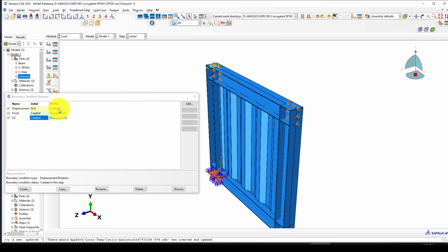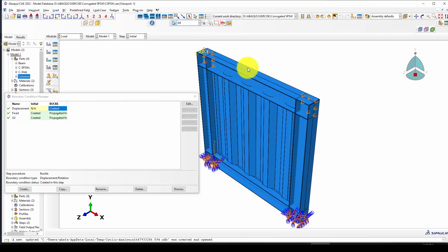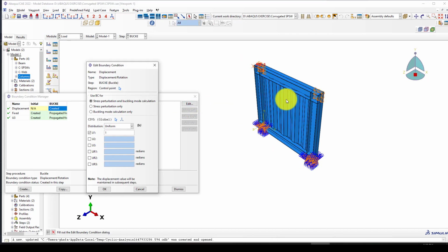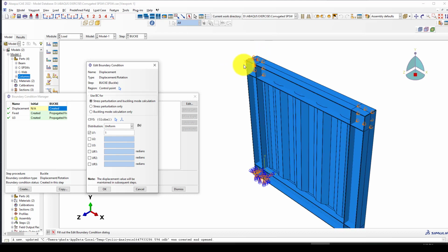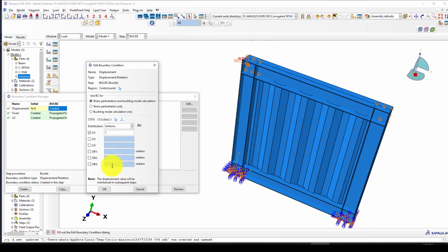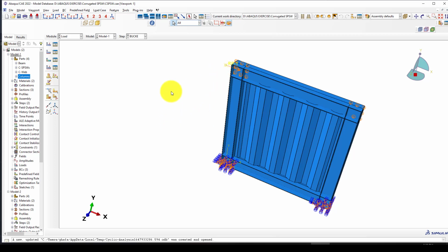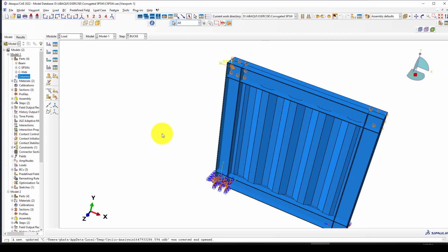Now in the buckling, instead of applying a buckling load, I want to apply a displacement. So the displacement is given as 1 unit at that control point, and we want to know, for 1 millimeter at the control point, how much the eigenvalue should be. Then the eigenvalue times the displacement gives us the total force needed to create buckling in this structure.